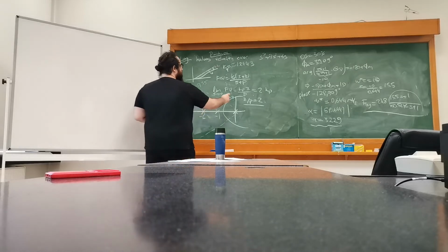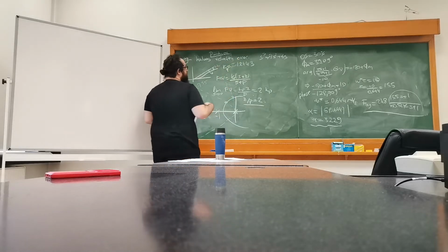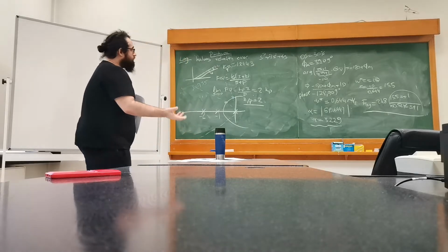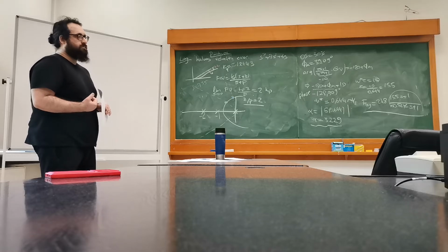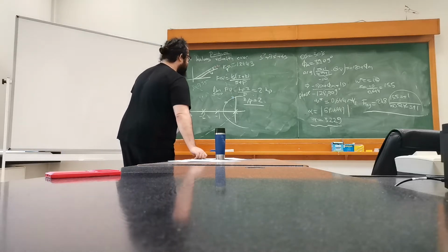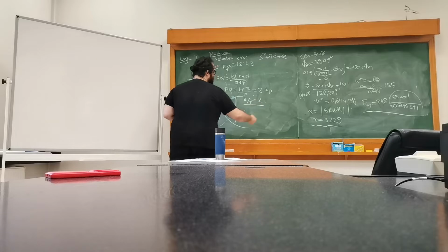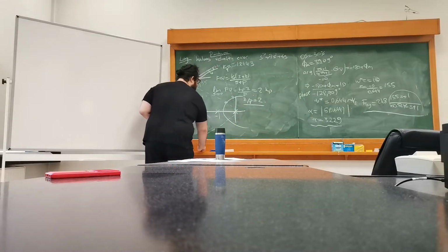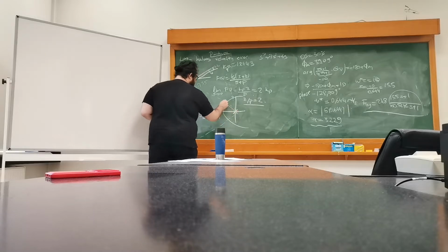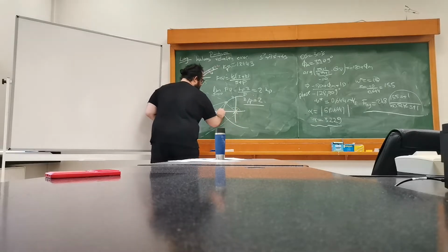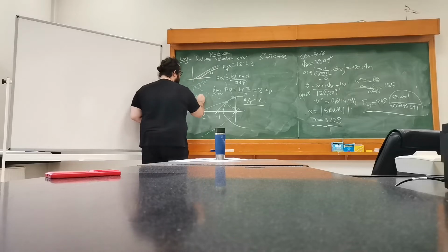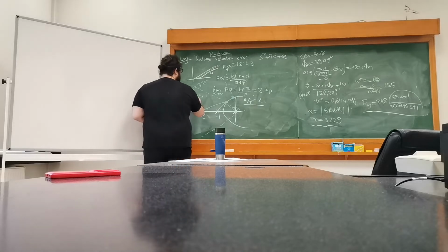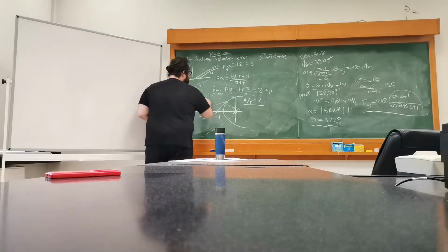But if I do this, my velocity error will be increased. The performance of the ramp response will be better. So I still want to do that, but I don't want to have high overshoot. So I have to design a lag controller, which has a Z-P ratio of 2. But now the problem is the following. Here, in terms of root locus, we have some angle contributions, and some of the angles are fixed to a certain value. And then we have the gain condition. There's also the gain condition that gives me exactly this point.